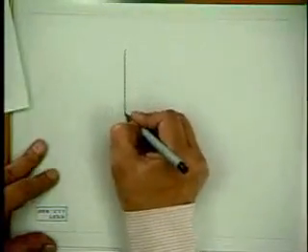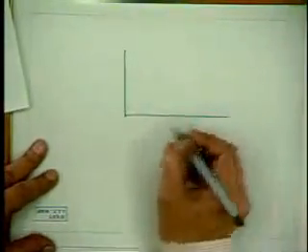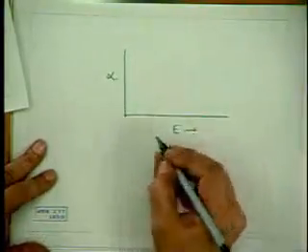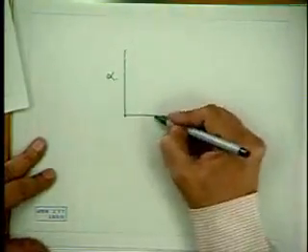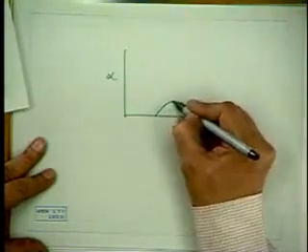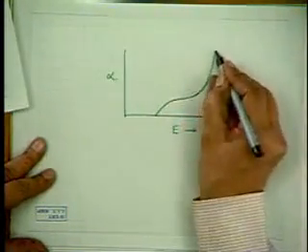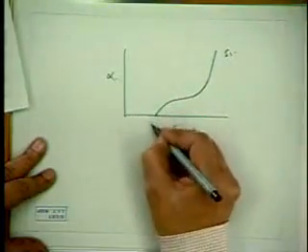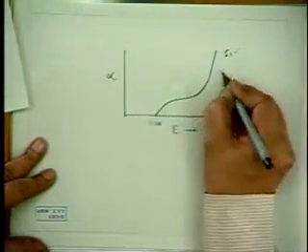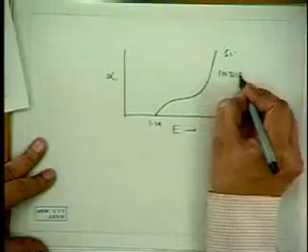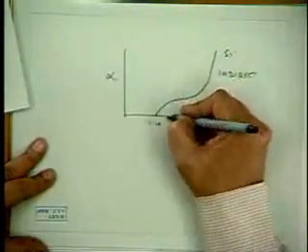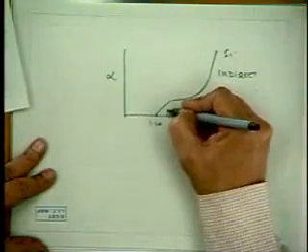As a result, if we compare gallium arsenide with silicon, alpha as a function of energy: for silicon the absorption starts at the edge, increases very slowly, and this is the edge of an indirect gap semiconductor, whereas for gallium arsenide the edge is at a higher energy but increases very rapidly.